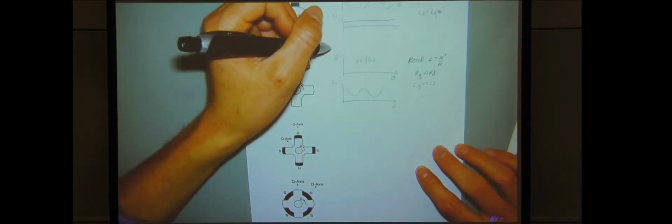So then if we plotted the inductance as a function of angular position, this inductance would be calculated where there's a stator as well. Just keep that in mind, of course. This is an approximation. It's not going to be a beautiful sine wave, but it's going to have some maximum and some minimum, corresponding to the maximum of LD and the minimum of LQ. So there's saliency.